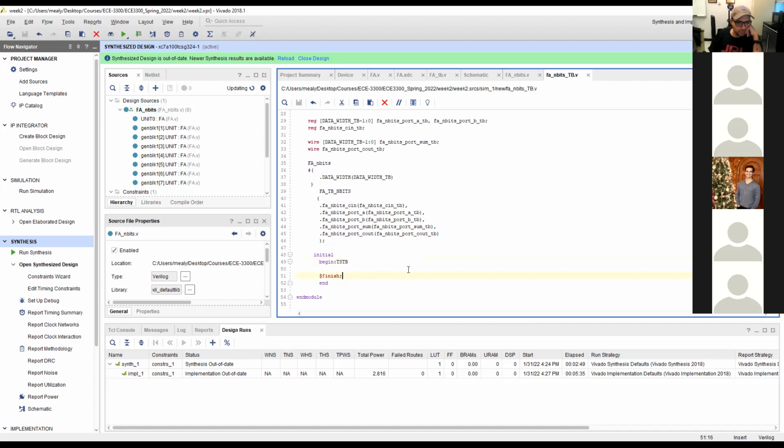So, to summarize what we have done, we talked today about a practical way to study Vivado, the connectivity between Vivado and the RTL perspective and simulation perspective, followed by the constraints and how we can connect the constraints into the RTL after it is tested, followed by some definitions in the language using the gate-level capabilities that we have to build a bigger circuit by concatenating instantiated components or modules, and then benefiting from the parameters, which are completely different from local parameters.